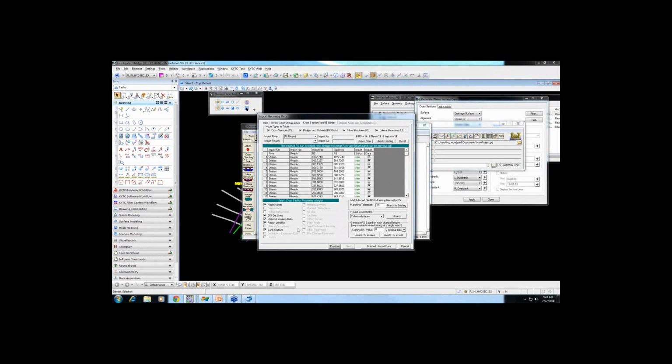So if you went into HEC-RAS and adjusted your bank stations manually after you brought it in, you could turn that box off and it wouldn't import any of the bank stations. And I believe the way that would work is that it would save your old data.